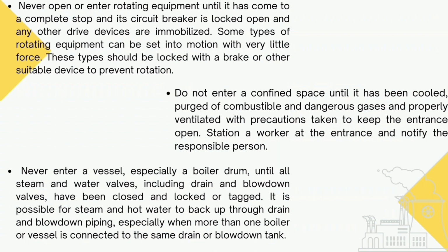Never enter a vessel, especially a boiler drum, until all steam and water valves, including drain and blowdown valves, have been closed and locked or tagged. It is possible for steam and hot water to back up through drain and blowdown piping, especially when more than one boiler or vessel is connected to the same drain or blowdown tank.